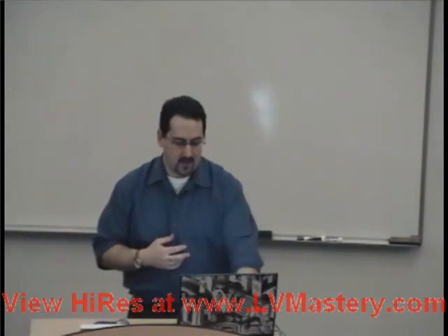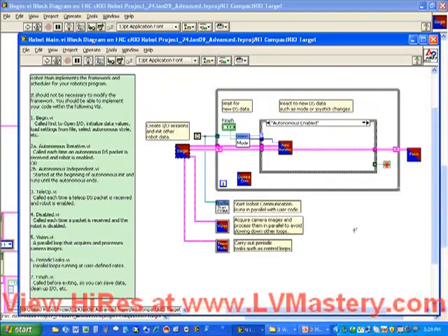The next thing I want to talk about is this idea of creating a debug VI. And let me just show you what I'm talking about. So I'll go back to my framework. The basic idea here is because of this shift register, because of this fact that all that data is being stored, kept, and reused. So I just jumped to the tele-op case because that's one we're actually going to run. We can create a VI that sits right here that allows us to monitor some important information.